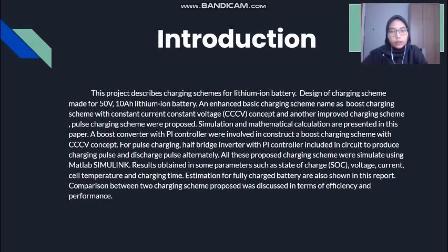Simulation and mathematical calculation are presented in this paper. A boost converter with PI controller is involved in constructing the boost charging scheme with CCCV concept. For the pulse charging scheme, a half bridge inverter with PI controller is included in the circuit to produce the charging pulse and discharging pulse alternately. All these proposed charging schemes are simulated using MATLAB Simulink.